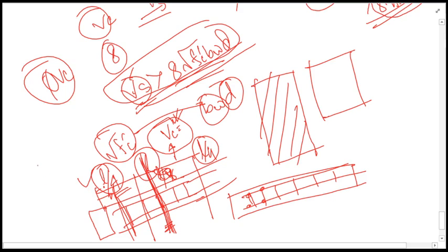So for each frame you will be getting one design, and for one design you will be drawing one longitudinal section and two sections, one at L by 4 distance, and another at the middle of the beam, and those two sections you will be drawing like this.